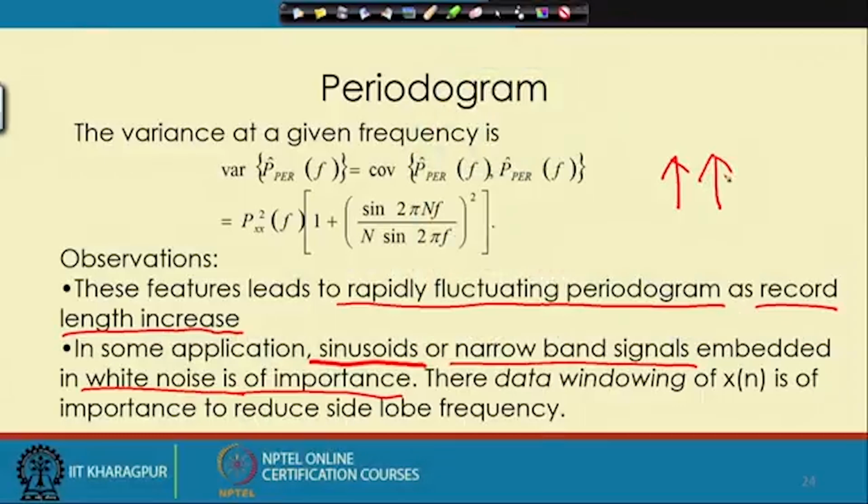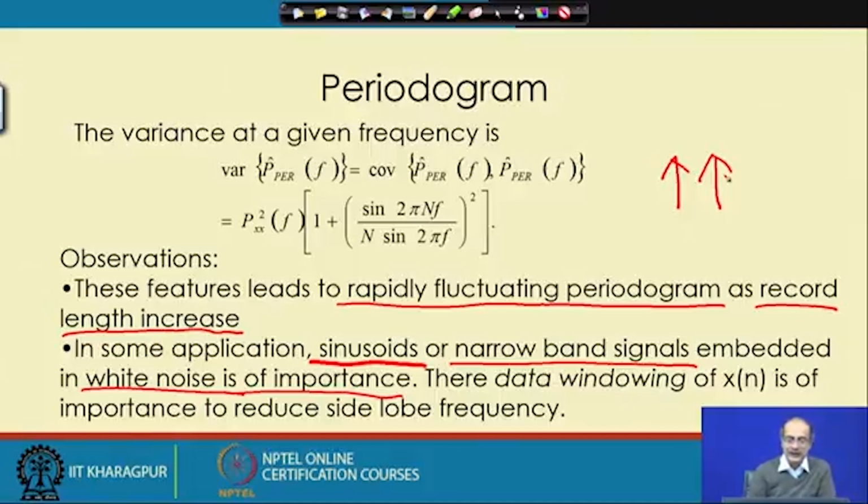The wave reflected from a stationary barrier would have the same frequency as the transmitted wave, and a moving target will give a slightly different frequency. So, two frequencies, or two impulses, we are supposed to get, which would be close by, and white noise is there, which has fluctuations.